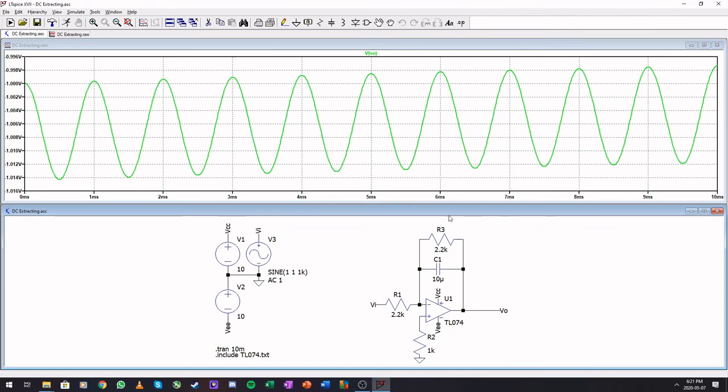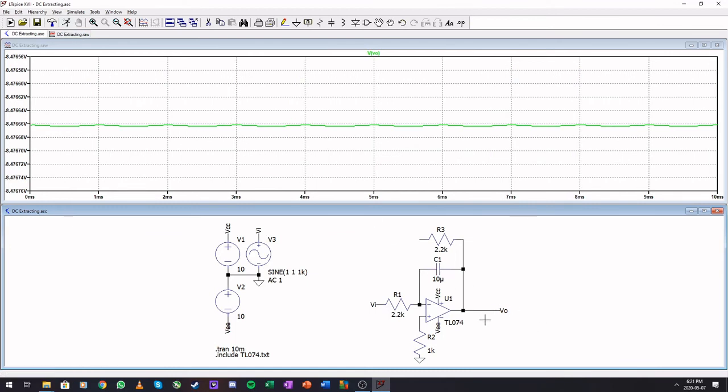And in the instrumentation amplifier, I used something similar, but I did not have this resistor here. So there's no load on this cap or discharge path or place for this capacitor. The output will not work. Okay, you can see that this amplifier goes to saturation. In the instrumentation amplifier, there is a resistor here where it couples into, and that counts as the discharge path for the capacitor. Okay, so that is how we do DC cancelling.